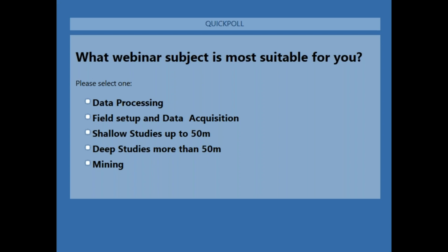So your depth coverage will all be related to the total cable section, like 100 meters or 200 meters. The only thing is the solution in the 2 pi or 4 pi, because at the water surface you have a half sphere, while inside the water you have a full sphere, in that case 4 pi, and that affects the calculation of the apparent resistivities.